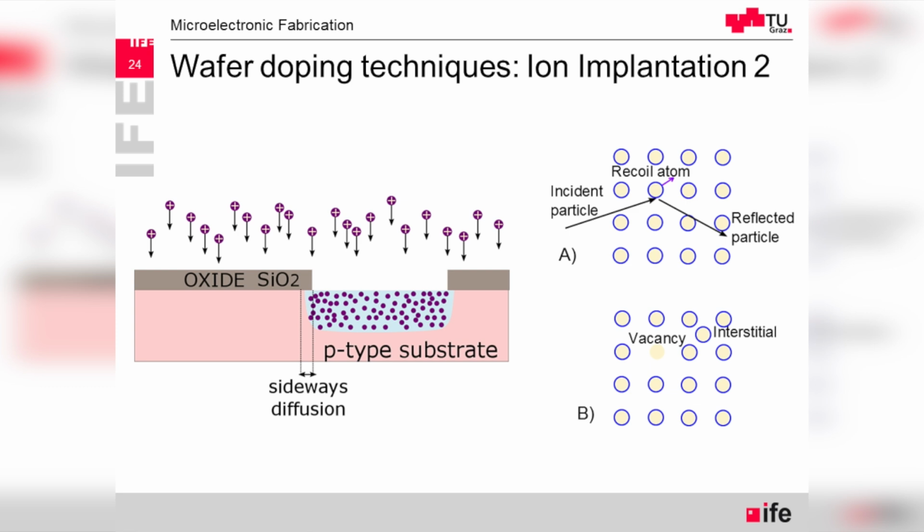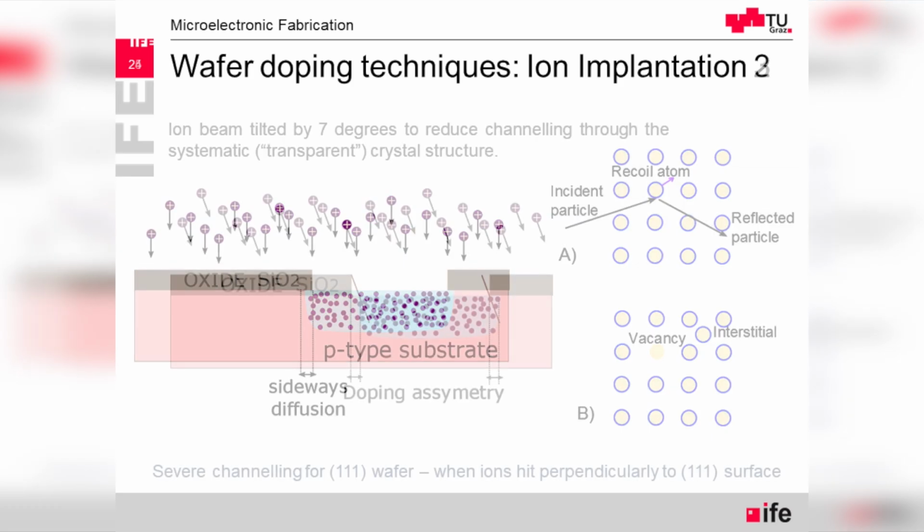But also, what's important, is the so-called activation: it's also necessary for the dopant ions to accommodate themselves in the silicon structure. So it's not only the process of repair, but also creating space for the ions in the crystal structure.